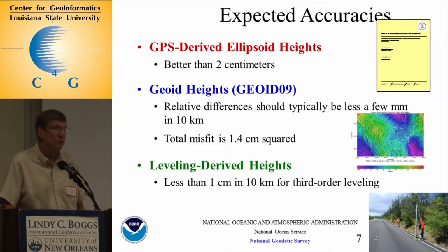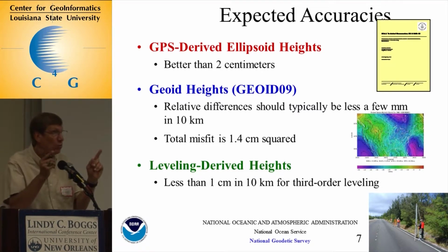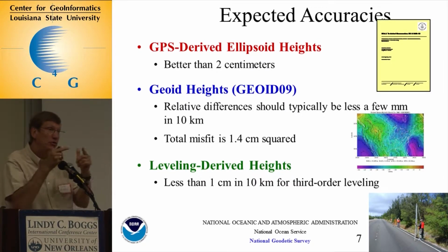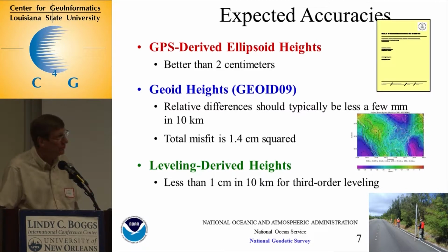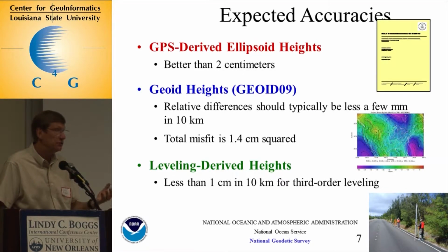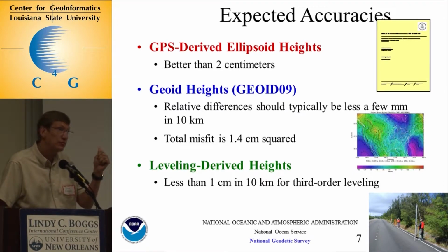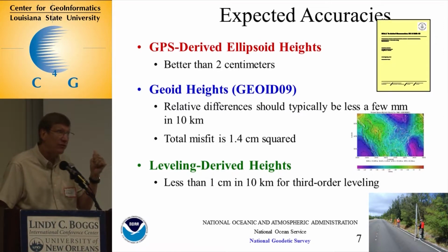because it's the process you're going through. Misclosure is one part of it, but if you level forward and you level back, and your misclosure is within that tolerance, you're actually taking the mean value. So your individual error in one level section is now meaned, and so you are taking out and removing some of the other errors. So you can't use the misclosure. Misclosure is not a measure of accuracy. It is just one procedure. You have to follow the procedures.